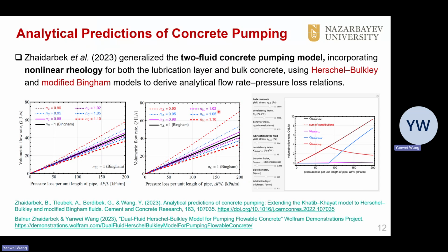This is where our recent work contributes to the development of concrete pumping. We generalized the two-fluid pumping model to account for the nonlinear rheology, where both the lubrication layer fluid and also the bulk concrete are modeled by the Herschel-Bulkley model or the modified Bingham model.